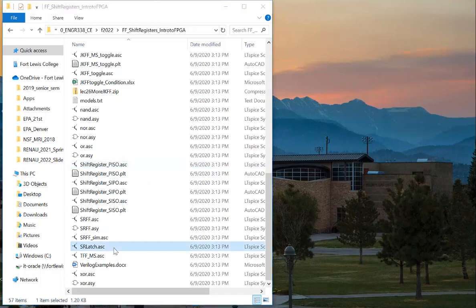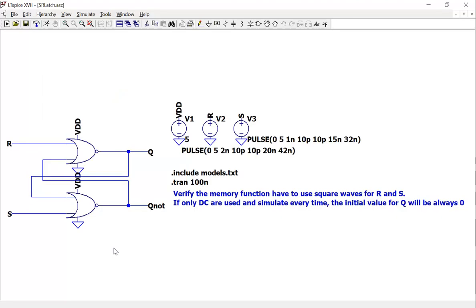That's what we did at the very beginning. So I'm using a pair of NOR gates as an SR latch. When you verify the logic of the SR latch, how do we want to design it? Because the combinations of the inputs could be 10, 01, 11, right? Let's just make it happen.